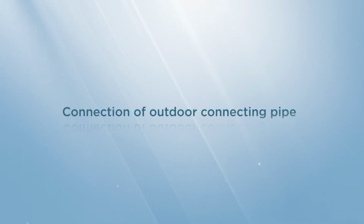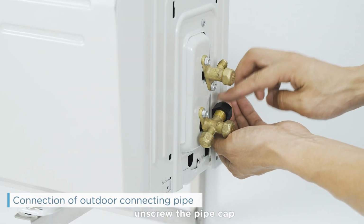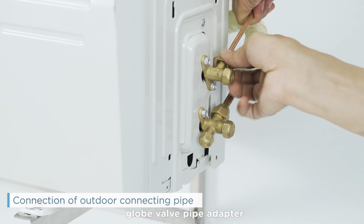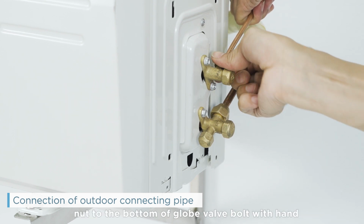Connection of outdoor connecting pipe. Open the cover of the water collector, unscrew the pipe cap. Align the pipe socket of the connecting pipe with the bell of the globe valve pipe adapter. Screw the pipe socket nut to the bottom of the globe valve bolt by hand.